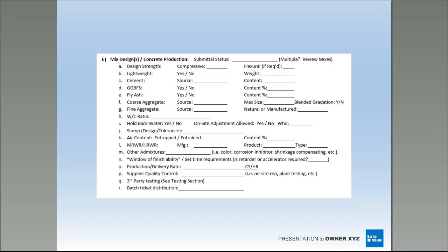So log that material and track it, and when I say materials, I mean the tickets themselves, what placement they were for, and the timeline of it. If you have that information, you could take that out to the pour, and you could almost go truck by truck, and it'll take you right to that spot you have a problem with, and you'll know what's going on with that ticket. So, hey, these are things you might want to ask for from your place finish guy to keep you in the loop on, because it's going to help you out. All right?